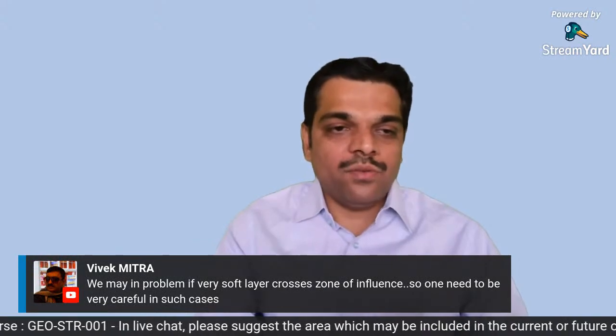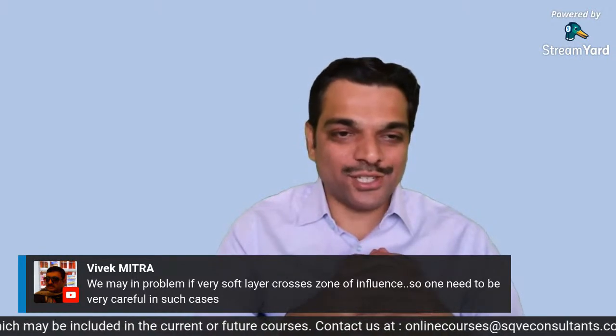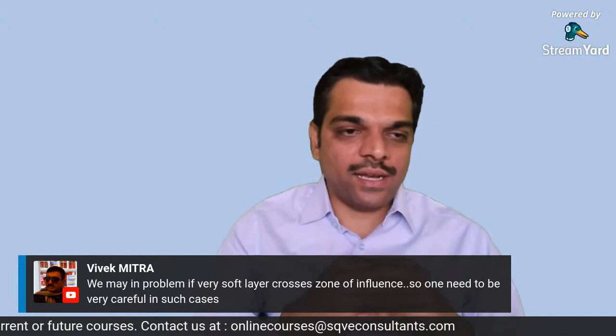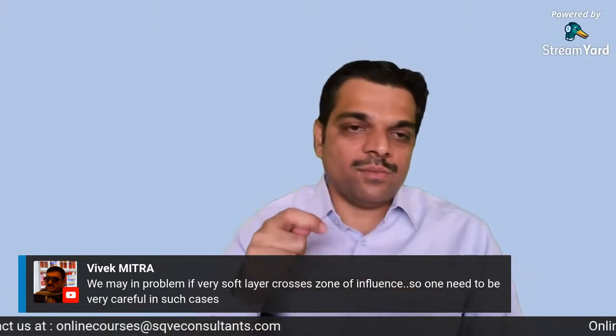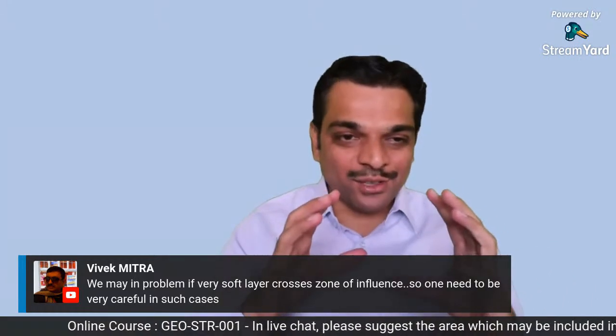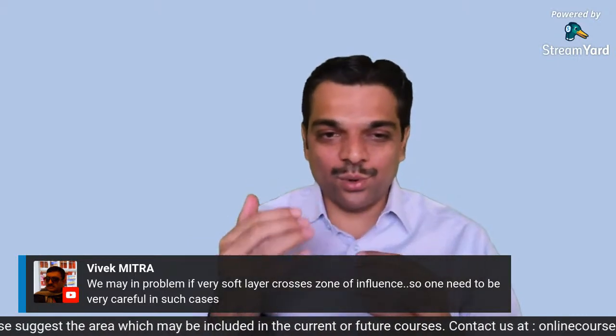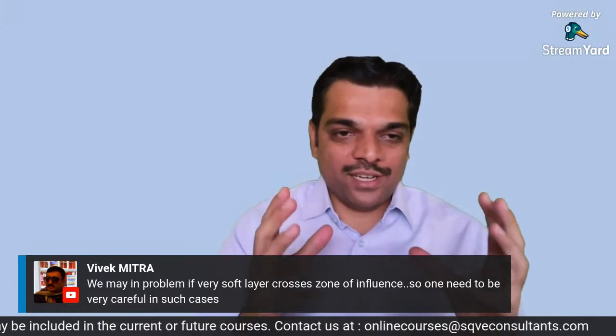Okay, yeah. Vivek Mitra is telling that we may be in problem if a very soft layer crosses the zone of influence. So one needs to be very careful in such cases. Yeah, perfect. That's why it's a very important thing, because sometimes I have seen a weak layer coming. Now, if I have a bigger foundation size, then the zone of influence could go into the softer layer, and if my foundation size is relatively lower, then I may not be going into this softer layer. So it's a very important area, and from that perspective the foundation design should be reconsidered.